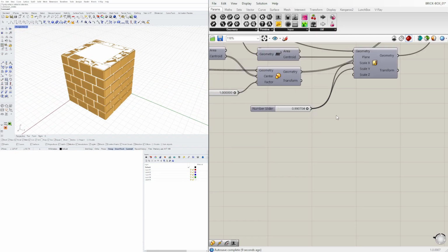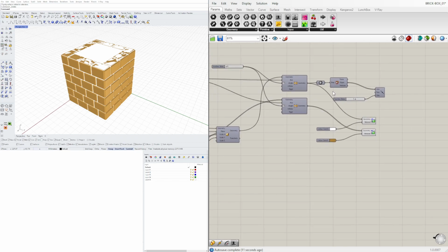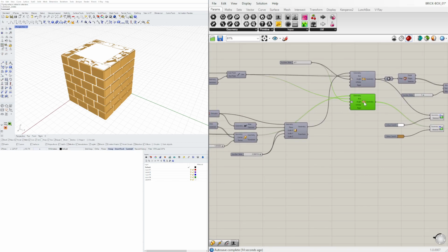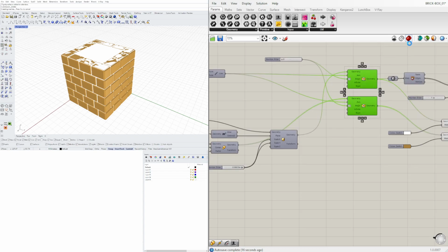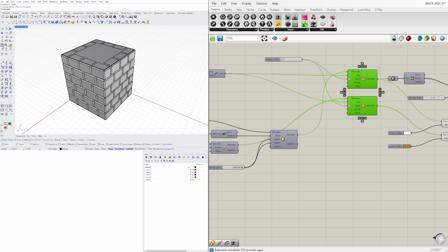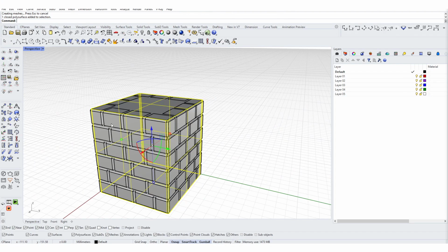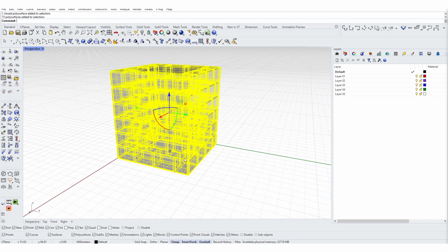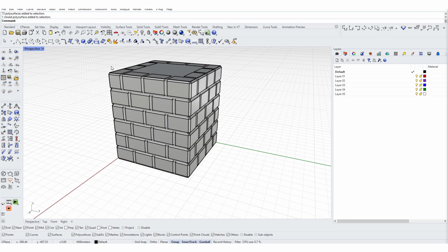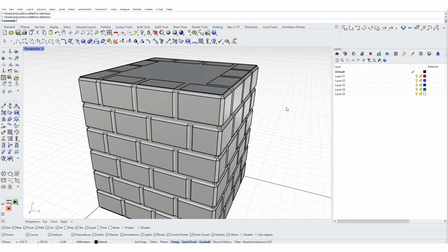So with this, what's cool is I wanted to be able to take the final result, which is going to be these two, middle click and bake. Now let's go here in Rhino, and I want to show you what I did to finalize it. So now that I have this and the bricks, what I did is I took this and I first extracted the face of this by, I'll go to this new layer and do duplicate face border. I'll select the top face and hit enter. This way I have a polyline that is the exact outside face of the mortar.